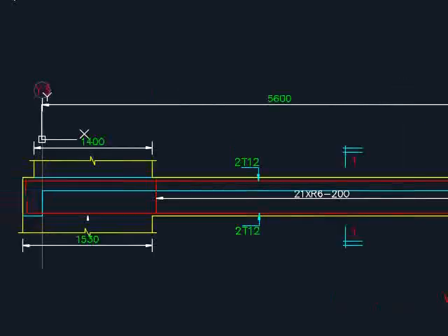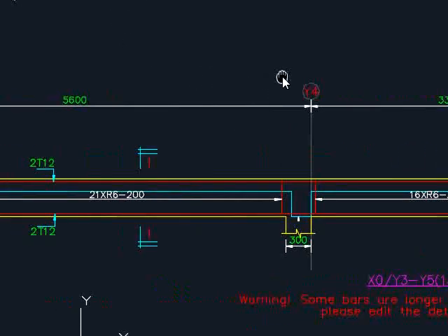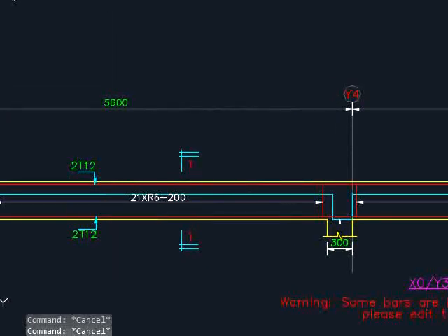And etc. There will be some needs for you to do some post-processing, deleting unnecessary or non-essential information so that your drawing looks neat. Probably clearly indicate what the reinforcement bar is here. In fact, it is only given in the other section, where the reinforcement bar is continuous. Automatically you expect this size and number of rebar will apply to the next span.